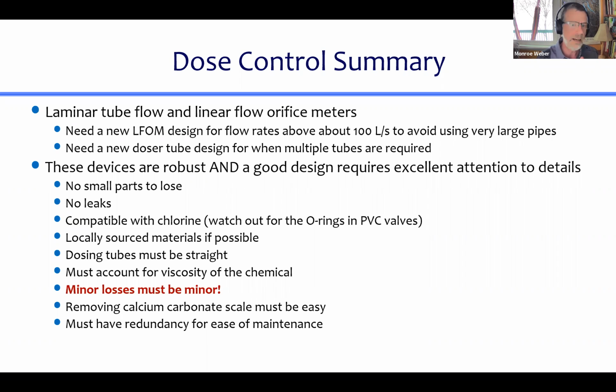I didn't show you, but we have the equations for the viscosity of the coagulant. The coagulant viscosity changes quite dramatically as the concentration of the stock increases. I don't actually have any good data on chlorine solution viscosity, but my first order guess is that it's very close to water, because the chlorine stock concentrations are quite dilute and they don't have the polymer effect that the coagulants have.